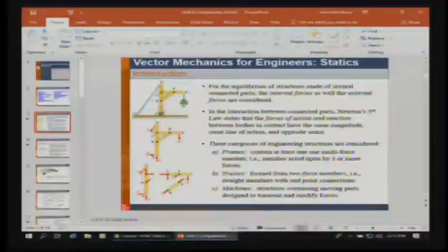For example, if we have this frame where we have a hinge here at C, and we have some sort of a supporting arm from B to E, and we have a weight here at F, and we have a guy wire from D to G, what we're basically doing is trying to distribute this load of the weight W so that it's borne on different parts of this structural member.